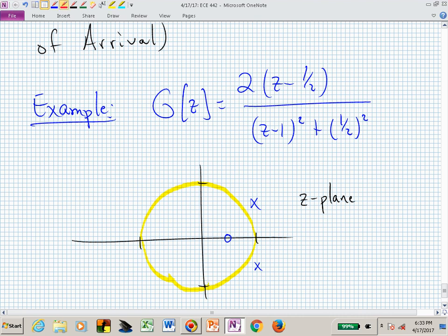And what's the root locus going to look like? This one actually you can do based on what you've already done with 2 poles and a 0. Another TV show. 2 poles and a 0. You could measure the radius from that 0 to those poles. And you could bring those down to be on the real line, but in fact, once you have this radius, you can now use your compass and you could sketch this. So this one didn't even really need rule number 5 to determine the departure angle.